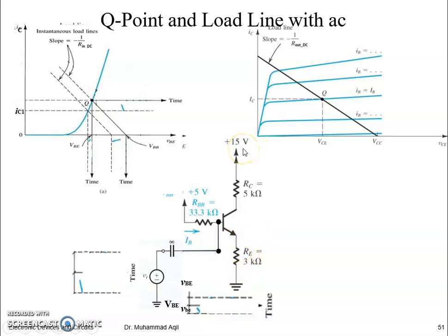So in this 15 volts, previously it was 6.9, 4 and 4.1, but this 4.1 will be reducing and this 6.9 will be reducing. It means VCE is increasing, because the sum of all these voltages should be equal to 15 volts. It means as IC decreases, the resistance between collector and emitter is increasing, or vice versa. You can say IC is decreasing because of an increase in resistance between collector and emitter. Anyhow, here we can see that as the base to emitter voltage, whatever it is, DC, AC or total of them, VBE decreases,